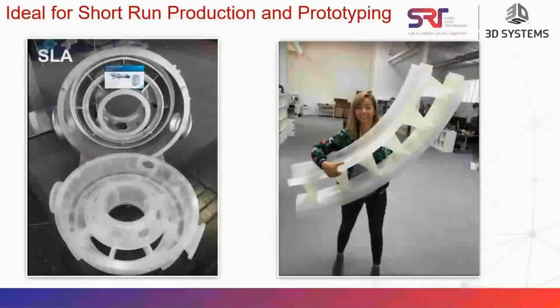Yeah, so this is a nice image of a QuickCast pattern. On the left-hand side, what you see is an 80 centimeter diameter gas turbine. The metal part is cast in titanium. The right side part is a segment component, one of the geometry. So actually, you have no real part size concern. That is the advantage of SLA. You can print a component of any size with this SLA system, because you can segment the component, print it, join it together later on, and then go for the casting patterns.